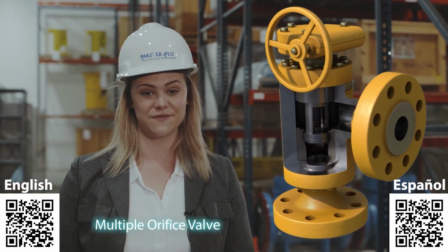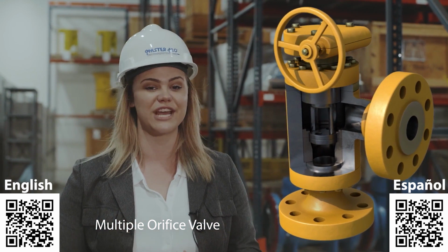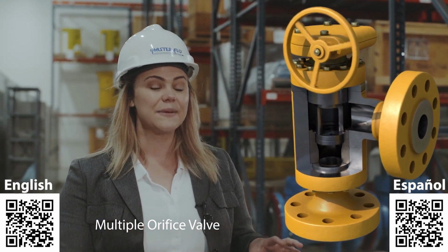The multiple orifice valve design allows for proportional changes in the flow. This type is most applicable when the upstream and the downstream flow are controlled at fixed points. This is not the case in nature. As the well is unloaded, the upstream pressure comes down and the downstream pressure rises.